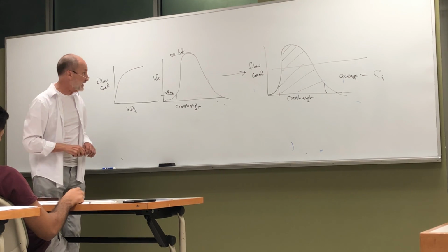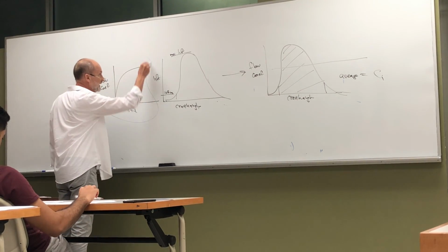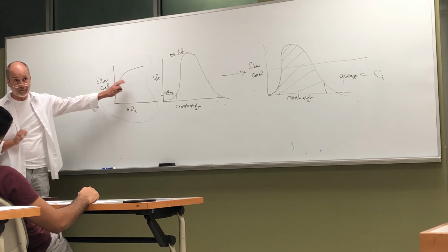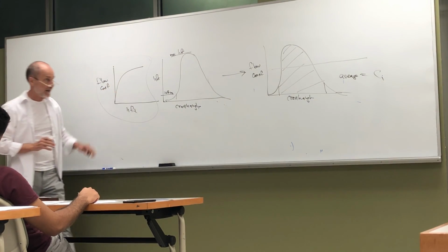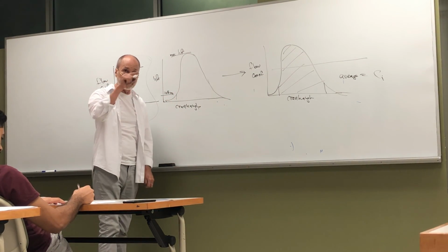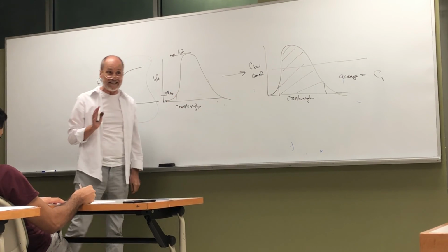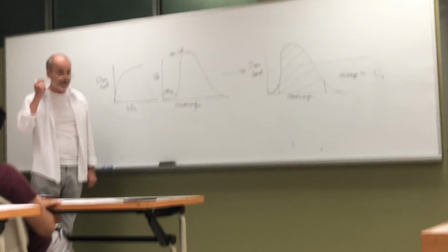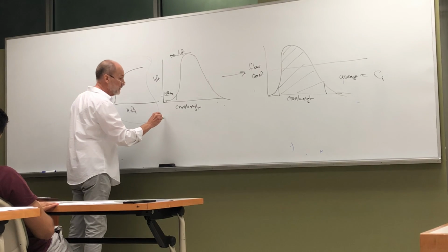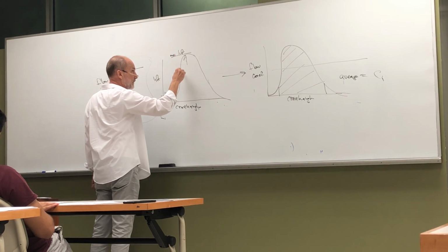This is the data that comes off of a flow bench. We do flow bench analysis, we get this data. If you don't have this data, when you degree a cam, you get this data. You can begin to estimate what the flow coefficient could be by taking the lift, the maximum lift here.